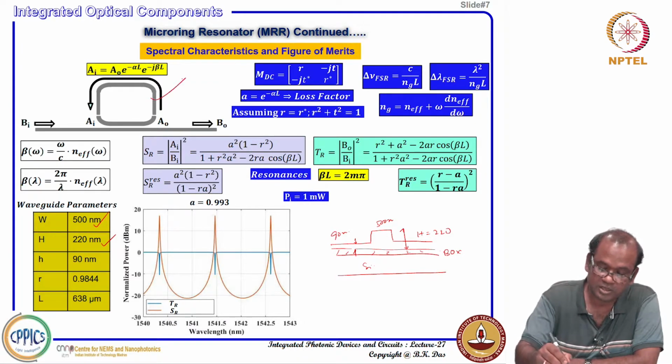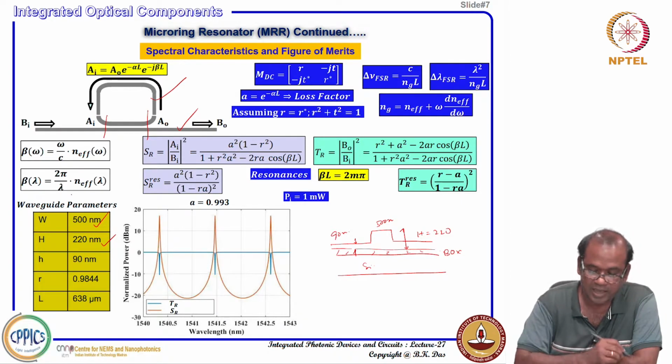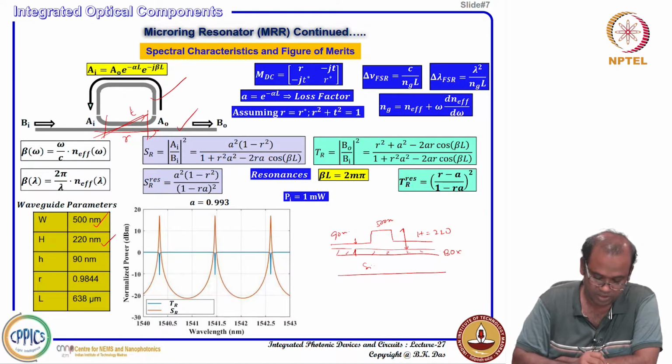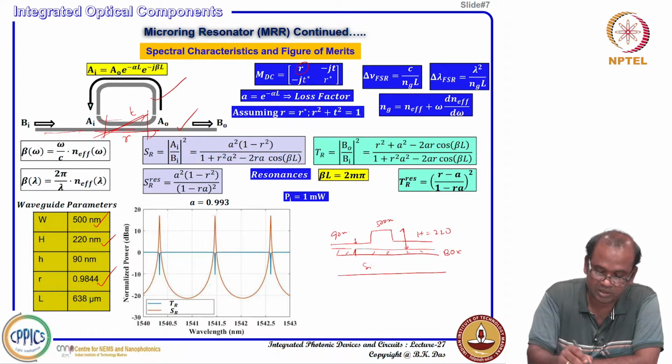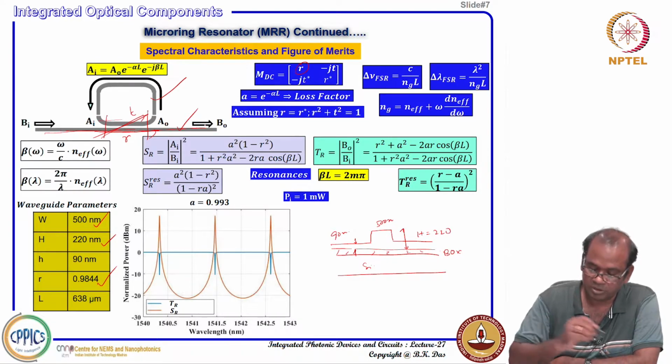Using this waveguide we construct the ring and bus waveguides, and if we choose a suitable coupling length, then we can consider how much will be self coupled and how much will be cross coupled. The self coupling parameter is R and the cross coupling is T. We have adjusted the bus waveguide and ring such that R, the self coupling, is what you get in the bar port of a directional coupler.